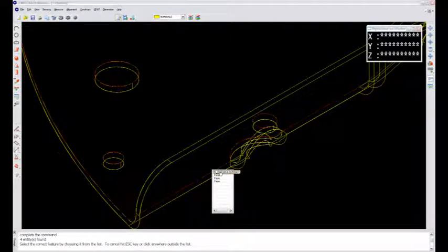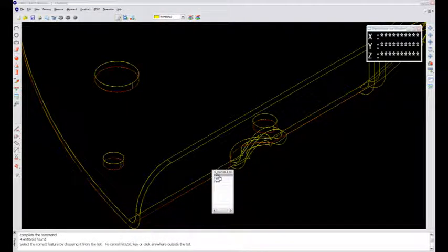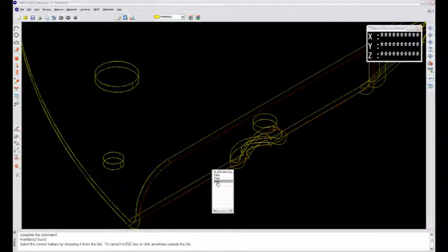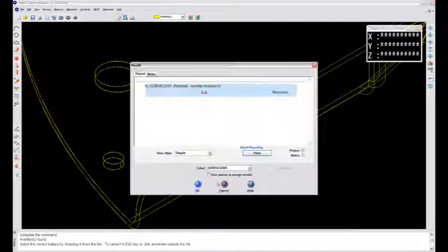Okay, it sees everything in its way here, the datum A surface. Here's a face that looks like the bottom of the plate. Okay, that looks like the upstanding flange on the outboard side. And there, that face looks like the upstanding flange on the inboard side. And that's where I've got a profile of a surface callout. So I'm going to click on that with my left mouse button.